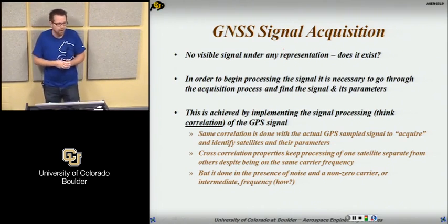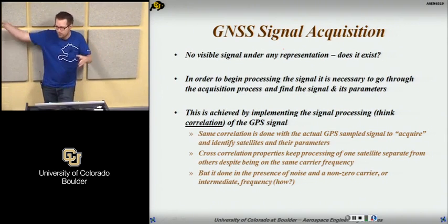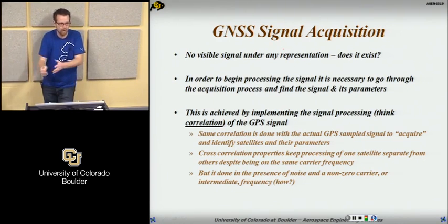So that was a good example of something being at baseband. When we talk about signal processing, people talk about things being at baseband. The thing is that the carrier on the signal should have been removed, similar to how the mixing is done in the front end. But that only gets it close, right? So we have a signal at 1575.42 plus a Doppler, and then we mix it in the front end. We multiply it with a sinusoid, and we move it down to another frequency, right?